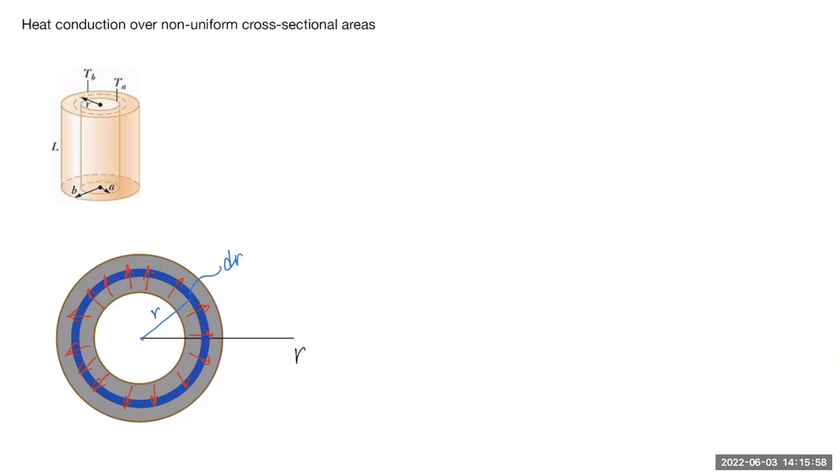There's a formula for that. So that is P equals K times the area, and then you have dT over dr. Okay, I cannot use delta T over delta R because we're looking at a very thin segment of thickness dr only. So the A is the area of this blue shaded cylinder. We're talking about a side area, okay? That is 2 pi R times the length, which is L, right? That's the cross-section area. And then you times dT over dr.